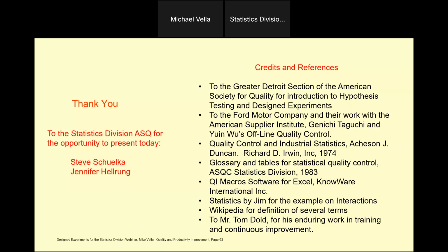I made the mistake early in my career of using an enormous experimental design with, I can't remember, I think it was 32 different variables. And the problem is it just took so long to run the trial. Because it took multiple days, multiple operators, and multiple lots of material, we sort of introduced more variation than we should have. So what you'd like to do is make it a very simple design.